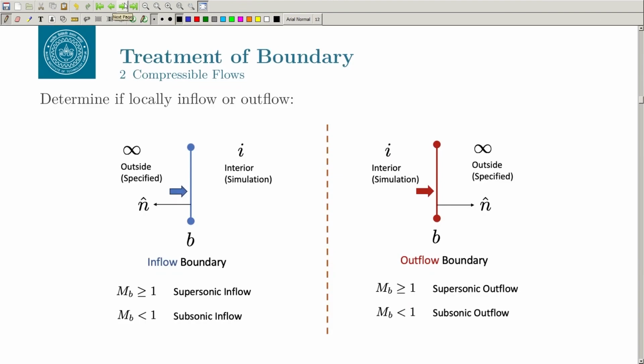Now, the compressible flow is slightly tricky. If you say compressible flow, your flow can be subsonic, supersonic, maybe hypersonic, transonic. There are different regimes, and flow phenomena change depending on which regime you are in. In the subsonic regime also, it can be very low subsonic or high subsonic. In the subsonic it is typically a Mach less than 1, but let us say Mach less than 0.3.